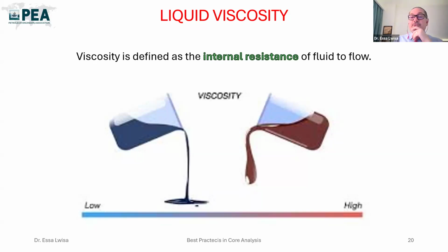Water is an exception to this rule. Its viscosity decreases with increasing pressure at constant temperature. For most cases of practical interest, however, the effect of pressure on the viscosity of liquid can be ignored, because the effect of temperature is much higher. Pressure will affect the viscosity of gases, but for most liquids it is ignored.